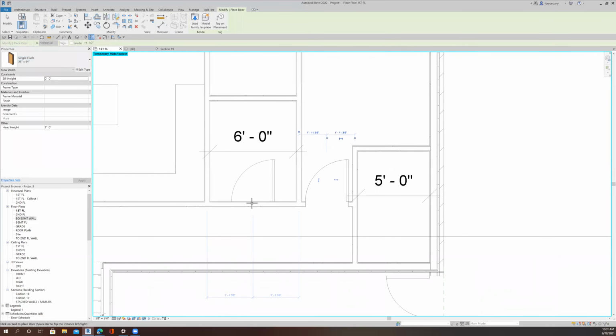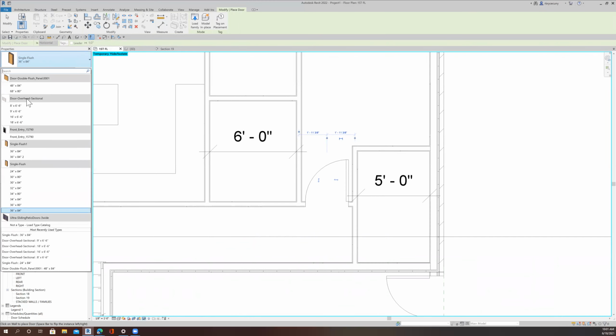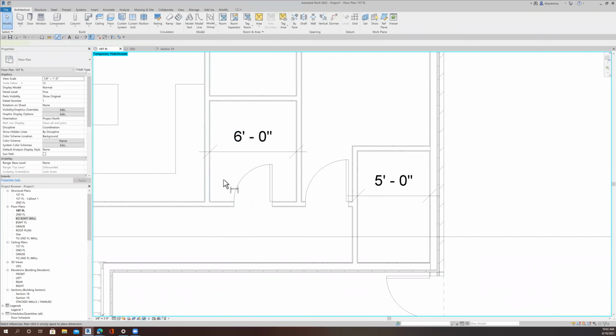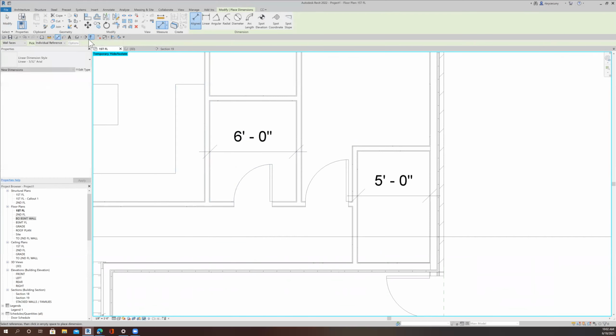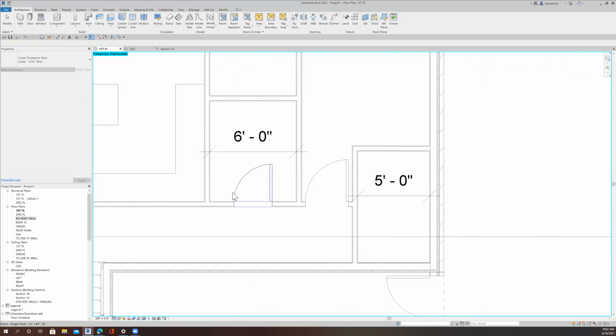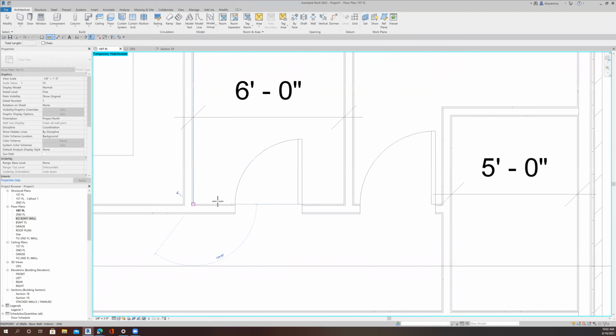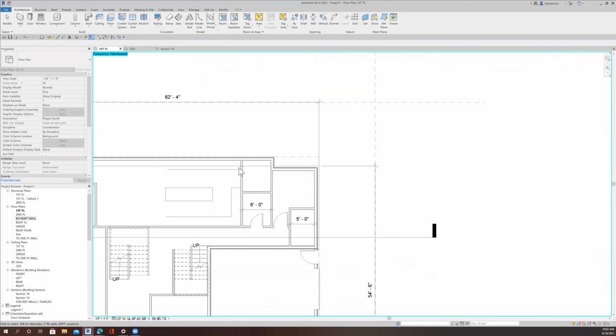And this is a closet, which is 6 feet wide. So a 3-foot door is probably not going to work for the hanging. A 2'6" or 2'8". Let's try 2'8". Put that in there. Okay. Let's just see. Let's center that door. See, my dimensions will snap to the center line. All right, so the door automatically centered. And let's just see what I got over here for distance. Probably okay for hanging. That's a closet, remember.